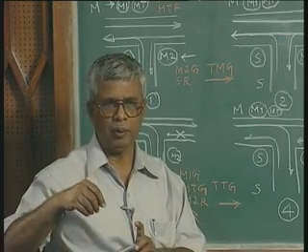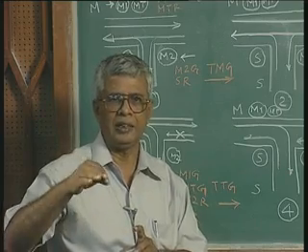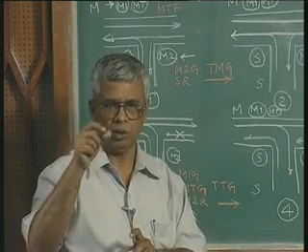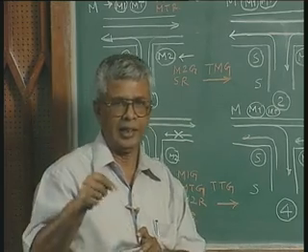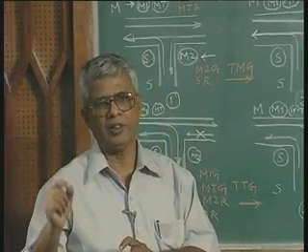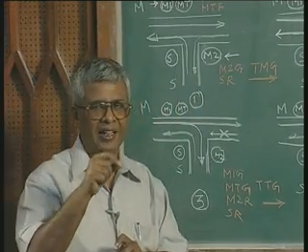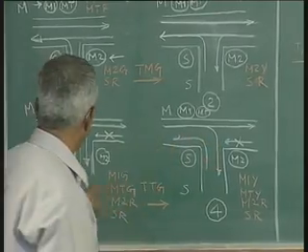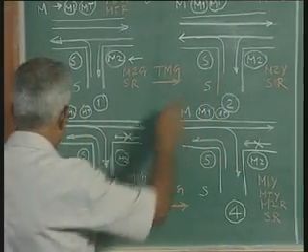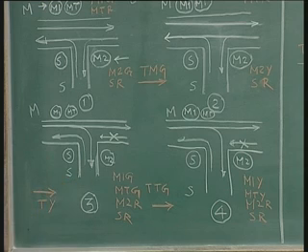To keep the specification simple, I am going to call it Ty. Ty is the time for which any light is going to be yellow, whether it is a main light, side light or turn light, before it becomes red. So after the elapse of Ty, from state S2 we go to the third state.